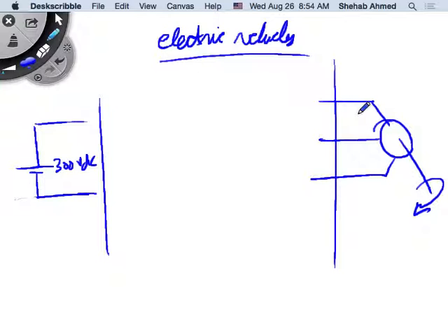Like the car's dynamo that is used to charge a car battery. It's based on a sort of DC type machine with brushes, right? The alternator. So it has brushes, right? These brushes wear out with time. They take a long time, but all they're doing is charging the battery, right? So the load is not very high. But the motor that's driving your car is a much bigger load, right? If you imagine having brushes in there, they would probably wear out a lot faster, so people don't want that. Reliability is an issue, one of the main reasons, yeah.